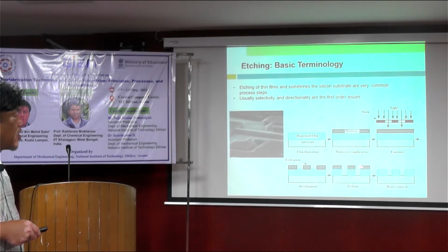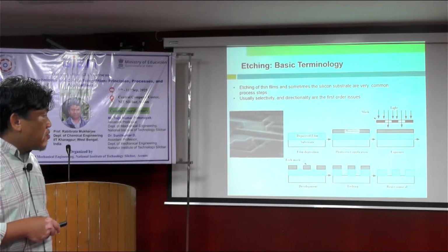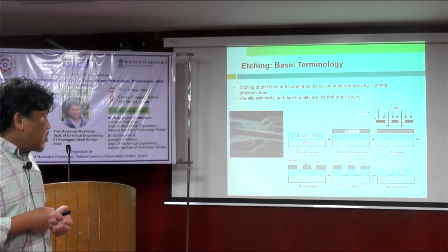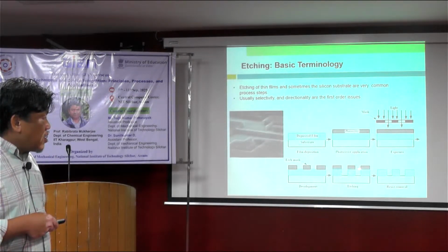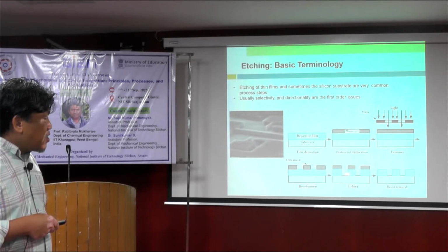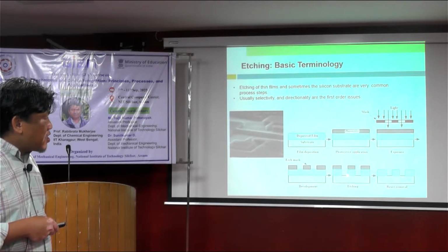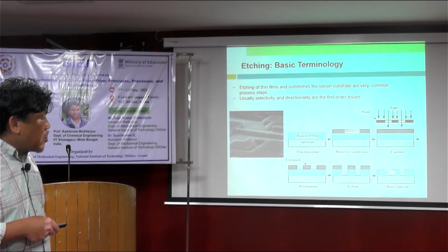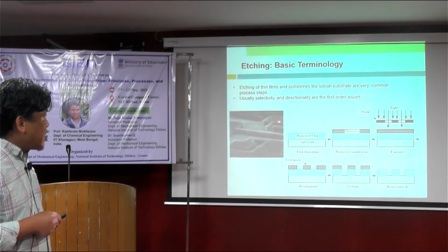If it's metal, for example, you want to have a circuit on this substrate. Then if it's gold, you might use gold etchant or some other. I mean, it depends on the materials. Then later on, once it's formed, if you see in this case, you might see that it's quite straight. In actual, it might have a different pattern, not that straight. But that is quite normal in the formation of using wet etching, but this is etching in general.